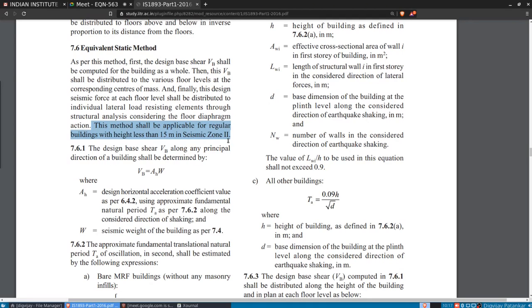So now if you switch everything, zone 5 becomes zone 4, and all the provisions need to be adjusted accordingly. So this will be complex. To avoid that complexity, they kept zone 2, 3, 4, 5 as it is. So now the entire IS code can be used as it is, except wherever zone 1 was there in the earlier IS code, that has to be read as zone 2. That makes things easier.